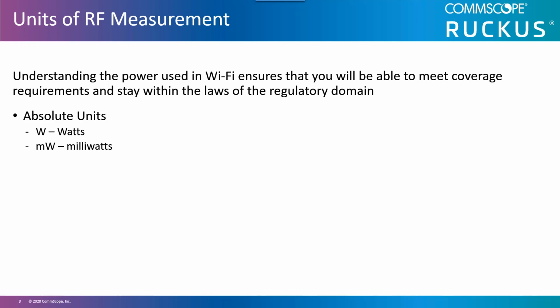This 100 milliwatts transmit power is before the antenna, so you must take care not to exceed the legal power output restrictions of the region within which you are deploying, since antennae are bidirectional passive amplifiers. In high-density deployments, you will find most APs are set to a much lower power level to reduce cell overlaps and co-channel interference.